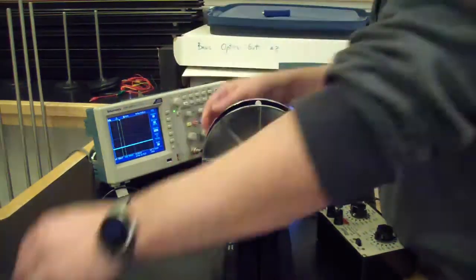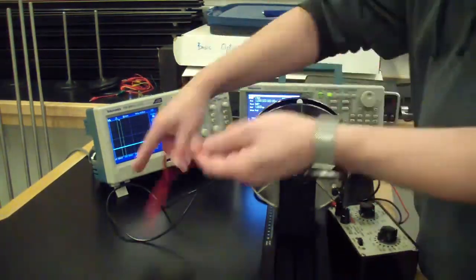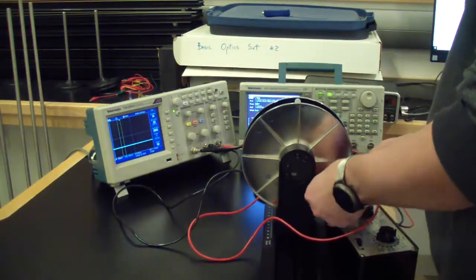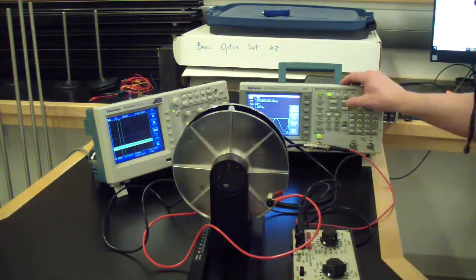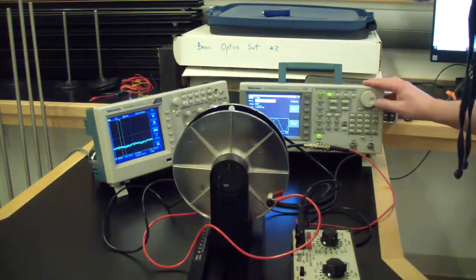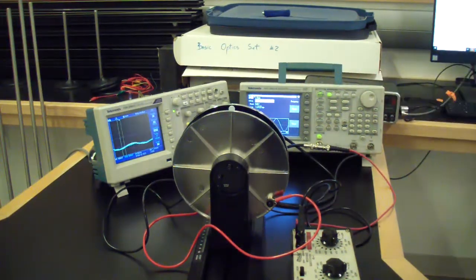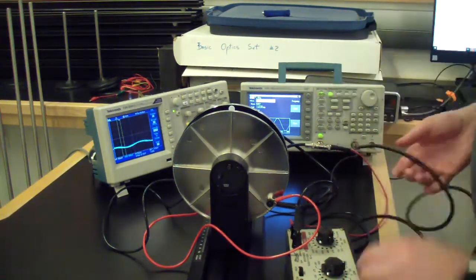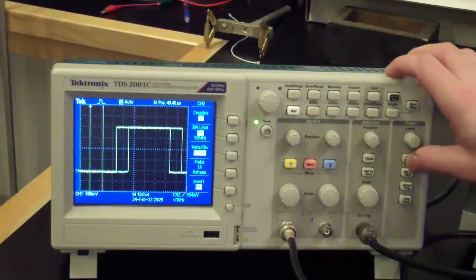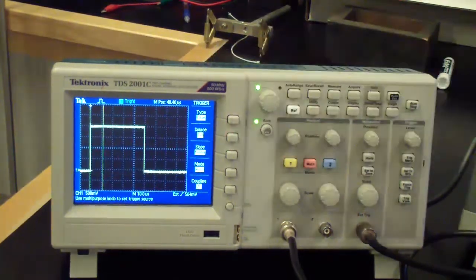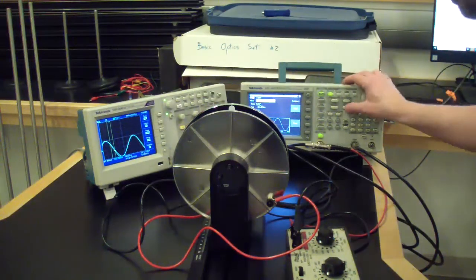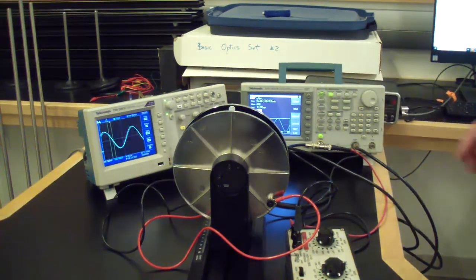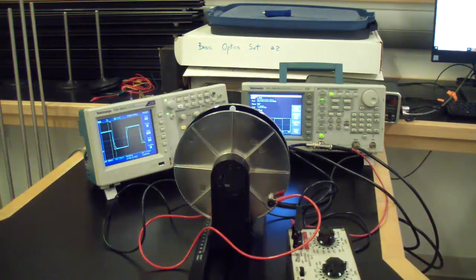Finally, attach the oscilloscope channel 2 across the two plates, making sure that its negative pin connects to the negative pin of the function generator. It may also be useful to connect the external trigger for maximum signal stability. To do this, you can connect the function generator TTL output to the oscilloscope's external trigger input and set the trigger to external. You should also choose an appropriate frequency, something below 15 kHz, set the offset to half a volt, and make sure you're outputting a square wave.